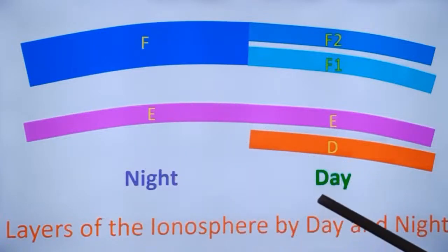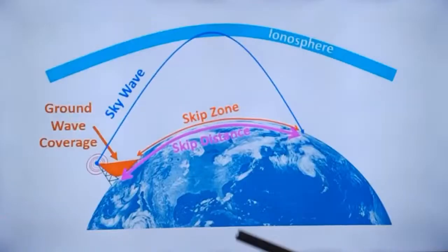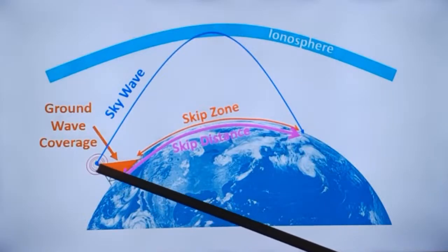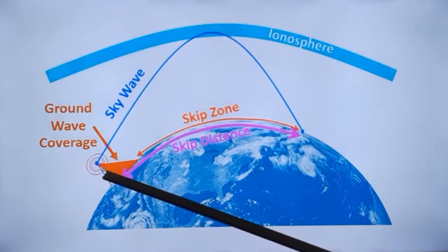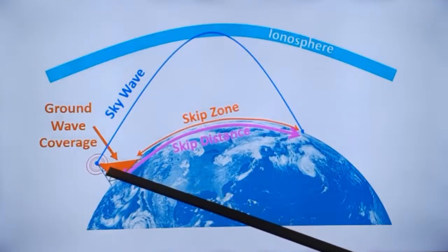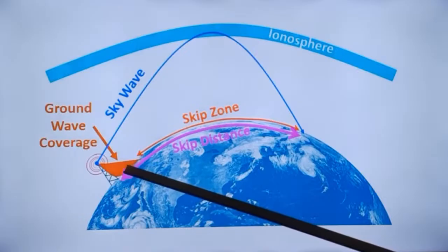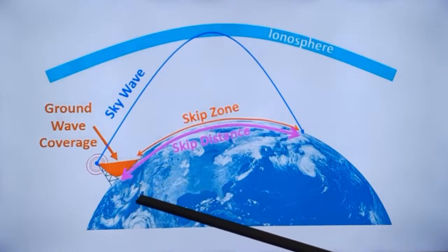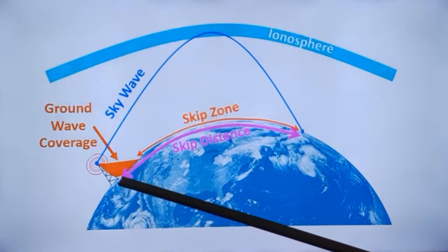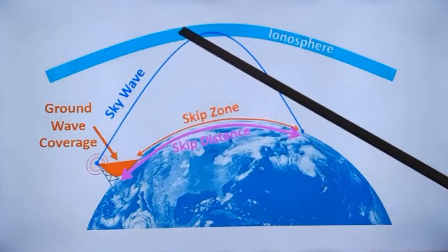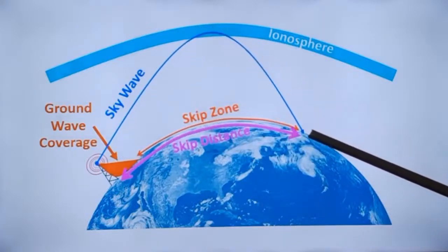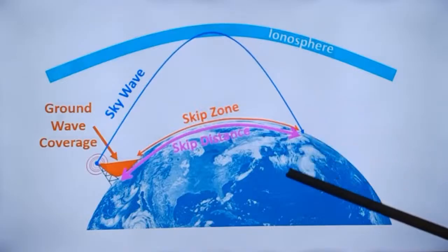That is skywave propagation, which I will show in another diagram. These are the sky waves which we are talking of. This is the representation of the ionosphere and this is the transmission. When there is a transmission, the ground waves cover only a small region. This is more commonly seen for medium wave transmission. And for short waves, when it is going at a critical angle, it will get reflected off the ionosphere and come back to the earth at a distance.